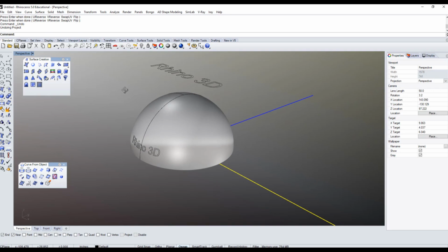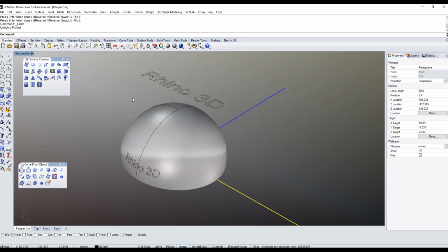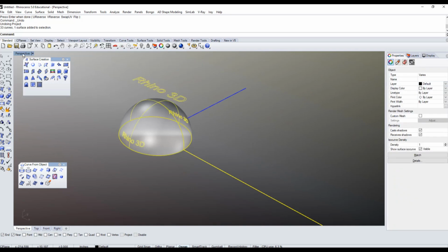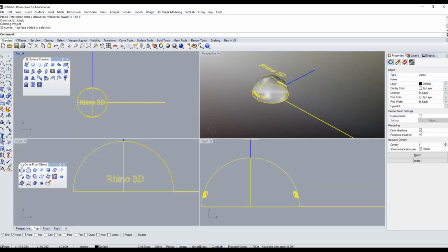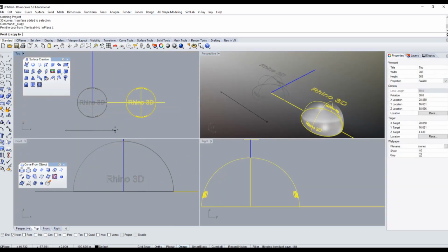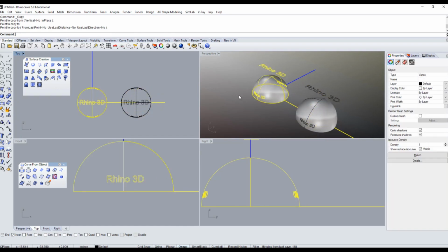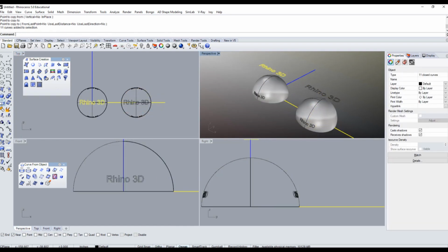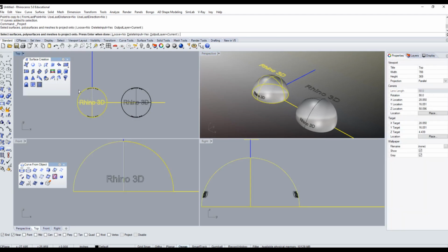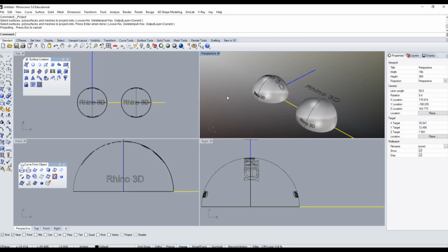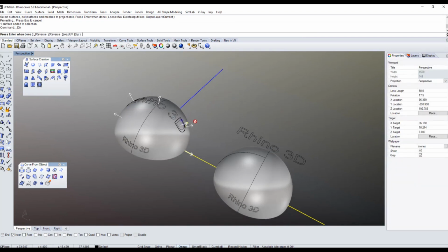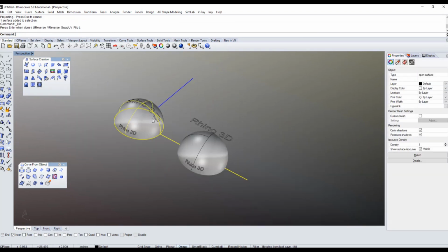And now I'm going to show you what happens with the pull tool, okay? What I'm going to do actually, I'm just going to make a copy so that I can show you side by side. So I'm just going to click on copy and go over here, right click, there you go. So I'm going to select the first set of curves again. I just click on project curve, I select my surface, I right click, and there's the projection. So if I click on the direction, you see my normals, how they're pointing.